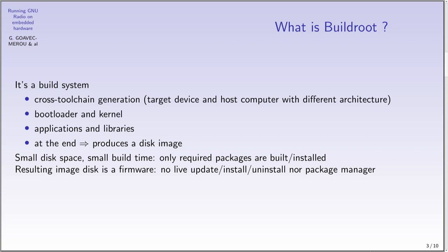The second task is to build a bootloader. Bootloader is quite equivalent to a BIOS, and the kernel to deal with hardware access. The next task is to populate the root file system with libraries and applications selected by the user. And at the end of the build, it produces a disk image. This file is used to write an SD card or SPI flash or an eMMC or a drive, of course.